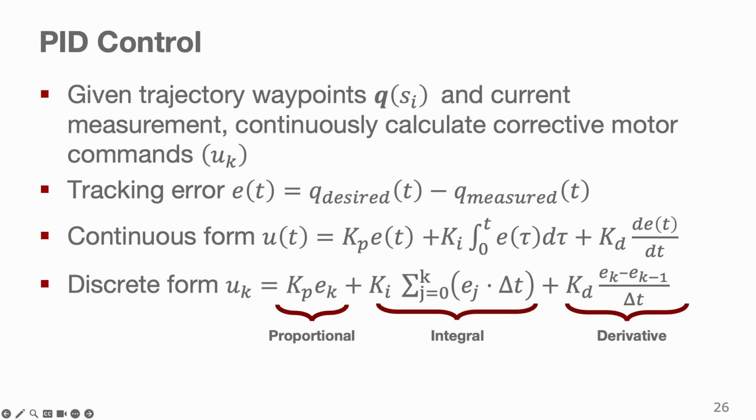But in the real world, the robot will never follow these perfectly just because you tell it to, because there are factors like friction, gravity, air resistance, and so on, that will make the robot not follow these waypoints perfectly. This is why you typically use a PID controller to ensure that your robot follows this trajectory of waypoints as much as possible.